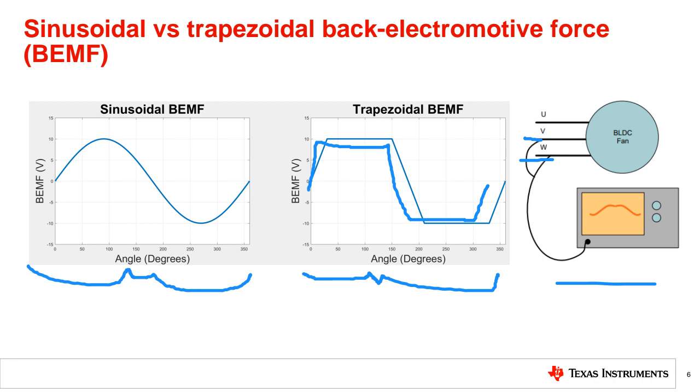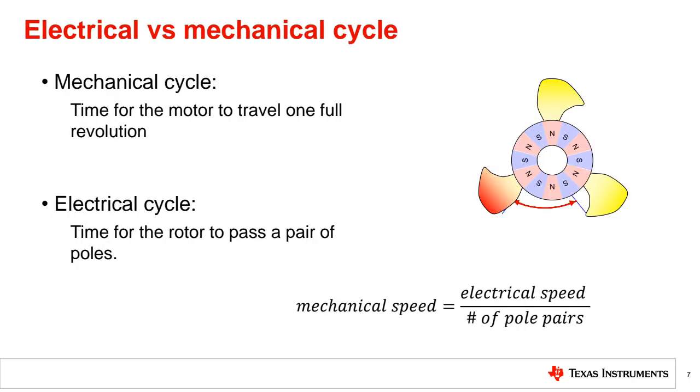When the permanent magnet on a BLDC rotor has more than one pair of north and south poles. Okay. Here we have an important point. I remember we discussed it actually. Mechanical cycle, electrical cycle. Okay. How can we decide it? The permanent magnet on the rotor of a BLDC motor has more than one pair of north and south poles, also referred to as pole pairs.